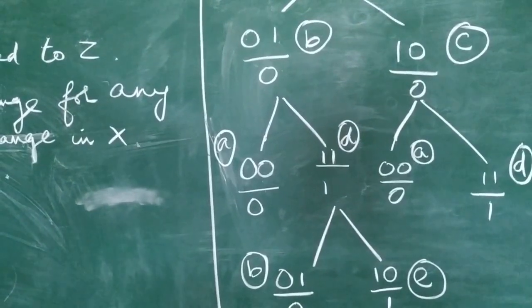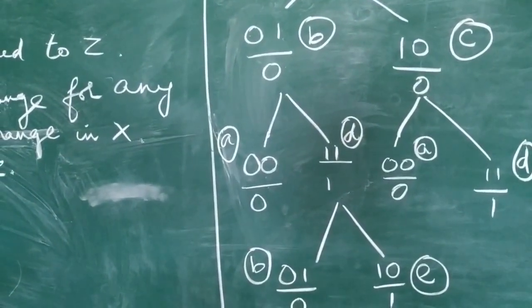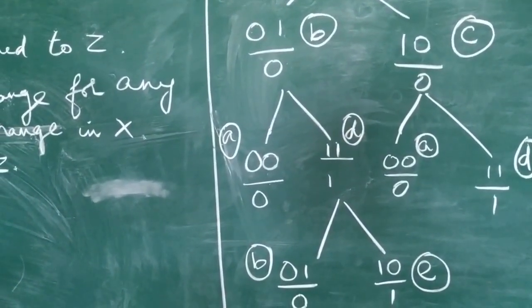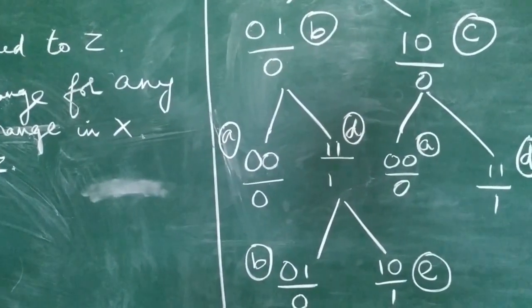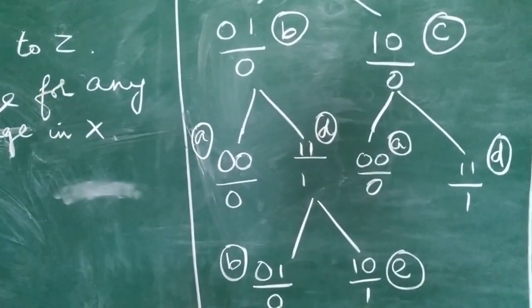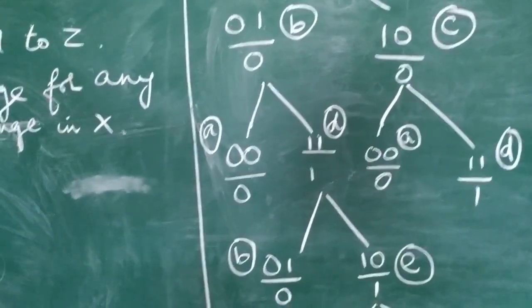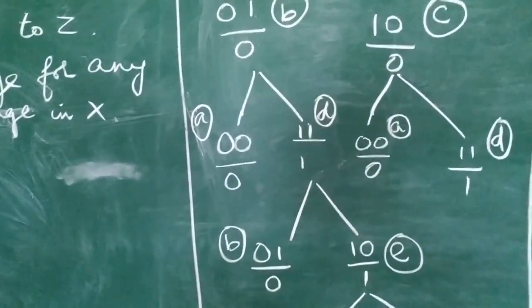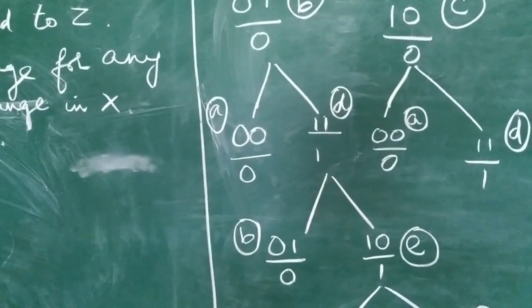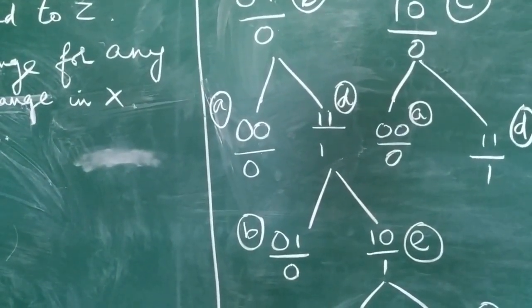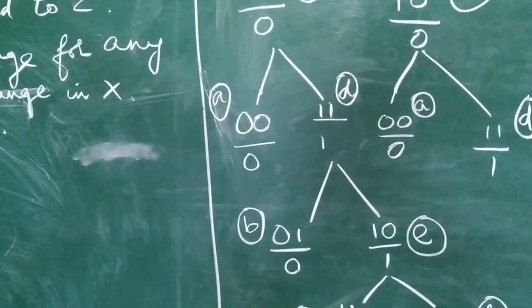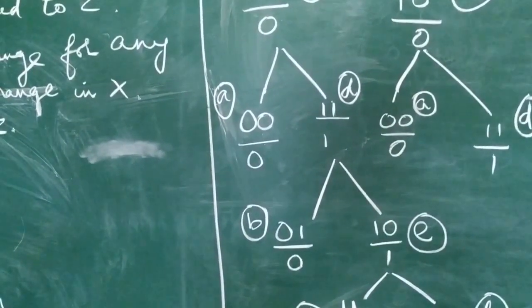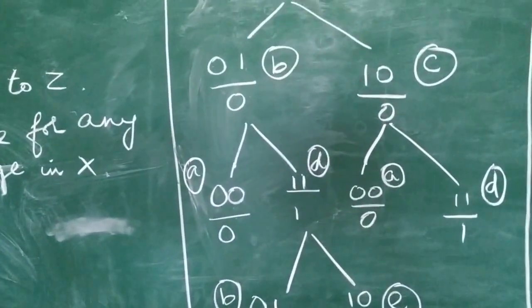So now a transition of 1 bit can occur from this B state very easily. So 0, 1 can make a transition, that is a 1 bit transition, to 0, 0 and 1, 1. A single bit transition only can occur, which I have given in the note. Now again you have to find out the output. So when y is equal to 0, the output is the previous output. What is the previous output?